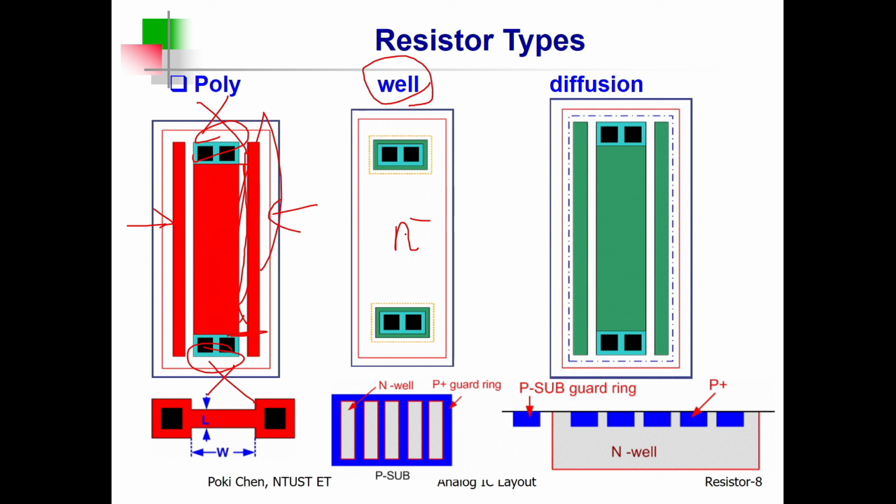I'm talking about the variation and the quality of the resistor. For well resistor, you need to face a lot of temperature effect. And after fabrication, to my memory, its variation is the biggest among all those on-chip resistors. So it's up to you. You can use a well resistor with very high resistivity, but you need to sacrifice performance.